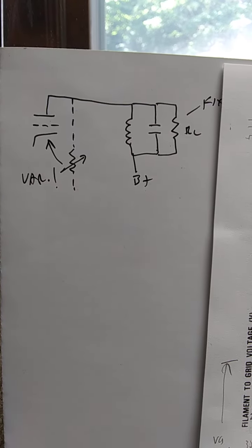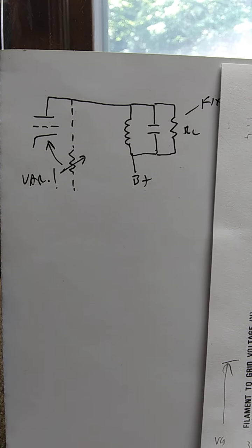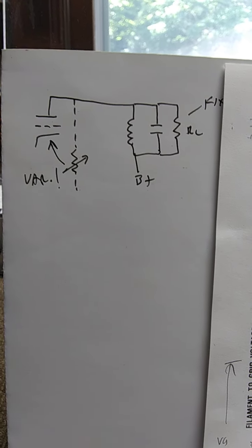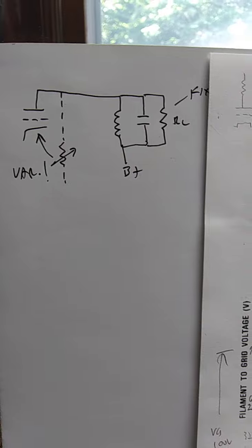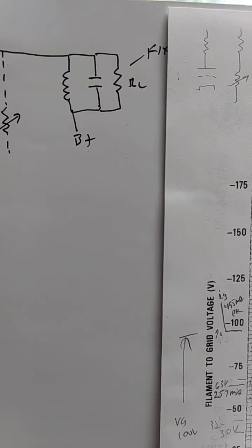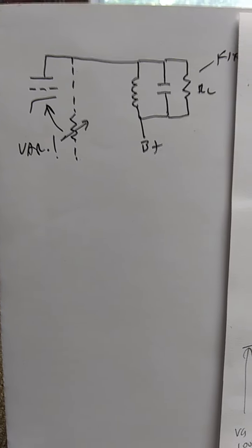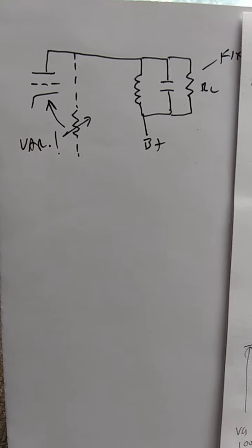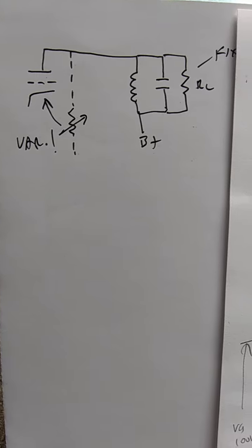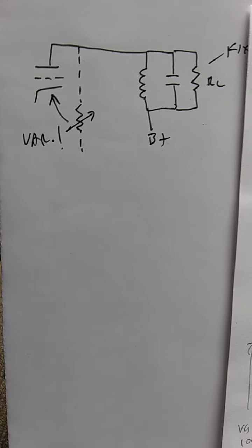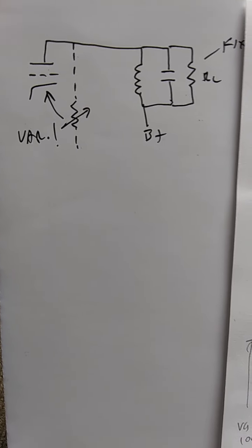That harkens back to the so-called tune plate, tune grid era. But it's interesting to note that in that case, the output to the final amplifier, in the case of the final driver, its plate circuit goes to the grids of the final tubes. That output's taken across this network, not across the tube. And it's difficult to see from the schematics. But there's a critical distinction that this circuit with a resistor in the plate will not work if there's a pi network across the tube, because the tube resistance is variable.